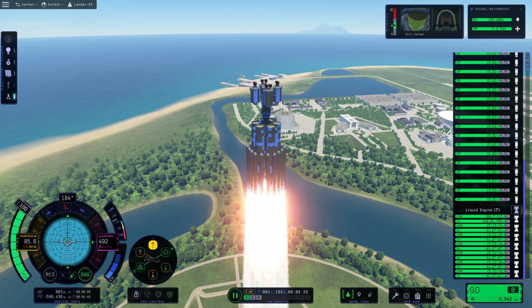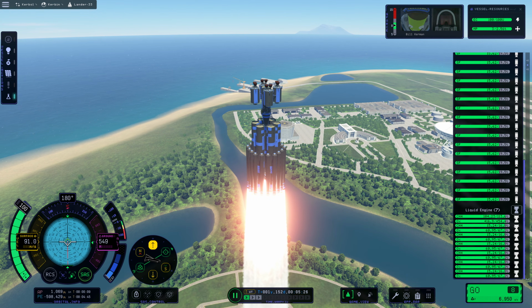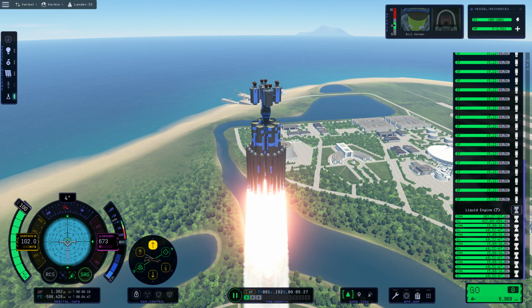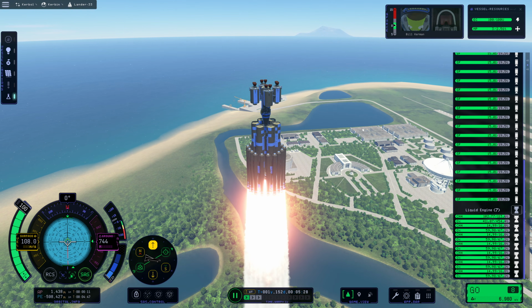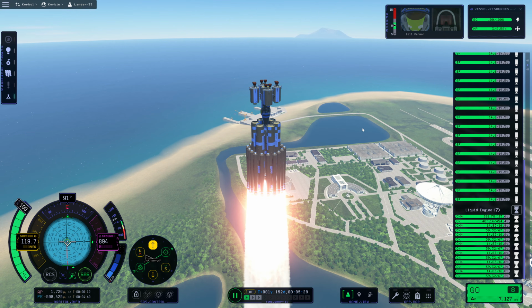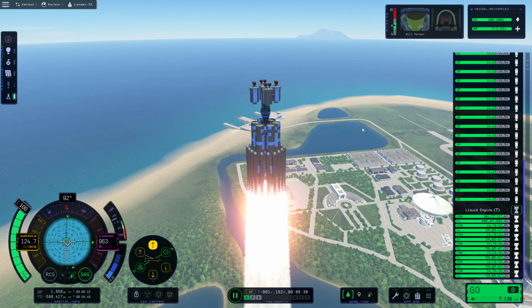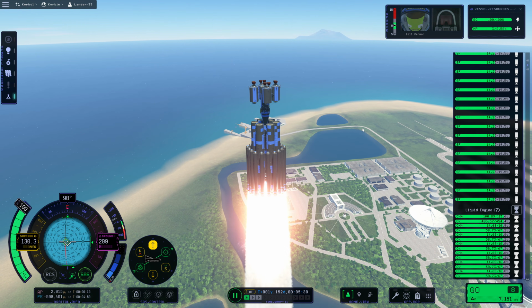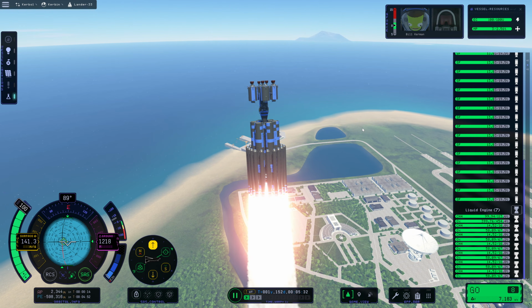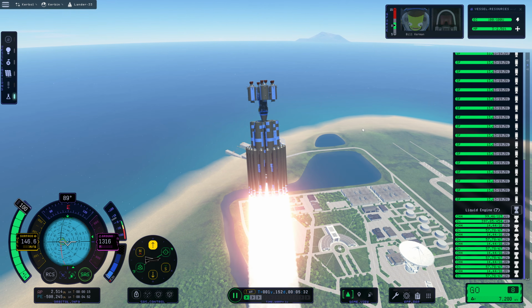We're going to continue to lift off here, and we're going to want to put this into a 45-degree angle relatively soon. Actually, maybe right about now. Let's start moving it over, because we want to have some amount of horizontal speed, but we also want to punch through the atmosphere. And we have a lot of thrust to weight compared to our previous iterations of this.